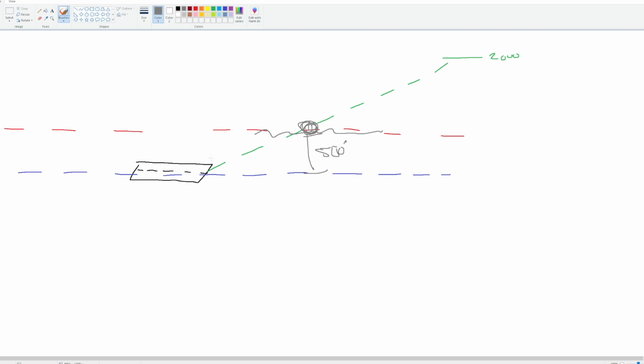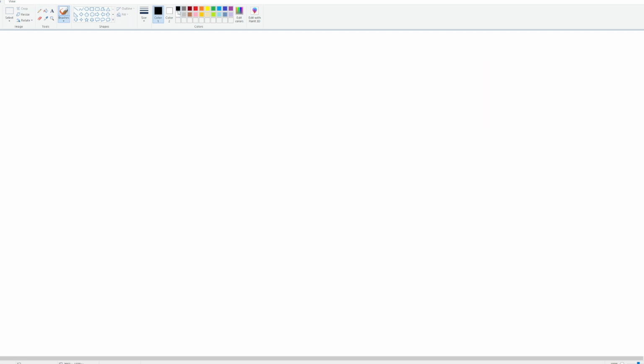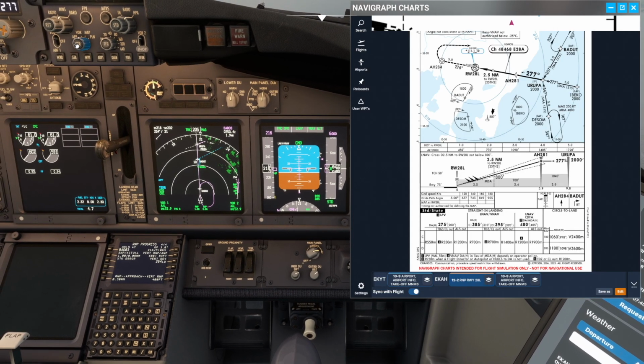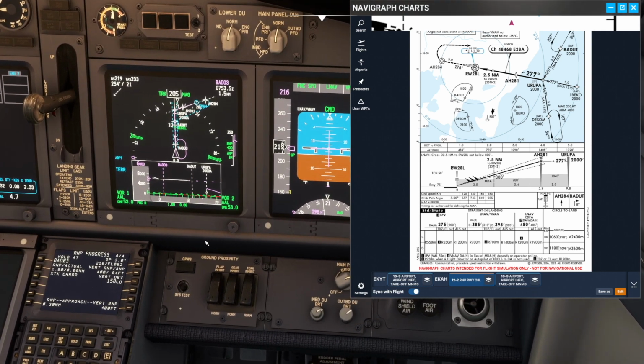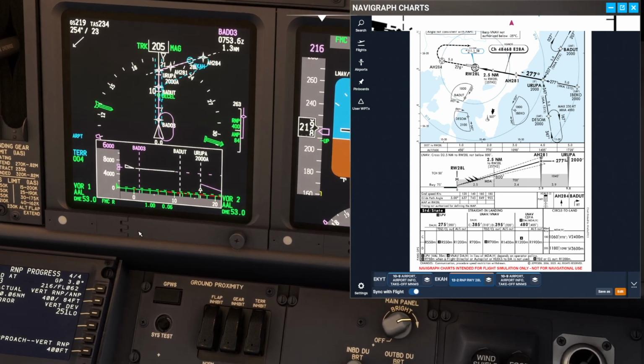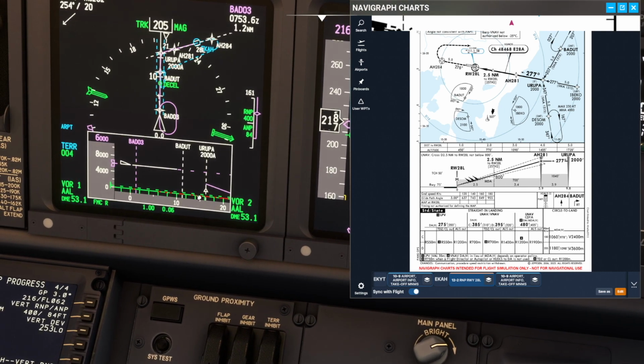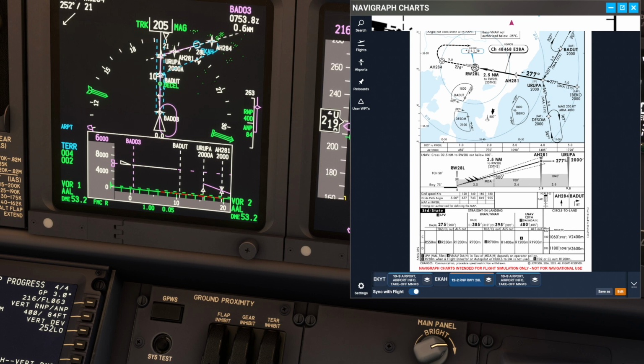And we can mitigate this. We can mitigate it in a few different ways. Let me create a new one here. If we have a look back in our flight simulator, we can see we have something called a VSD. On the VSD, if we zoom out far enough, you'll notice that when it has loaded, you can see we have a terrain line here. Now there's no terrain around this area, so it's quite flat. But this terrain line, we should have the runway placed right on top of it. That is our main way of mitigating QNH blunder error.